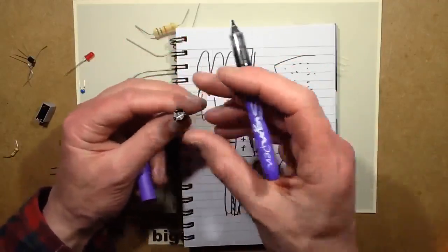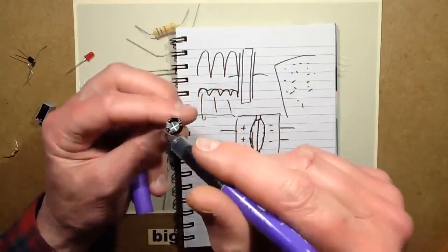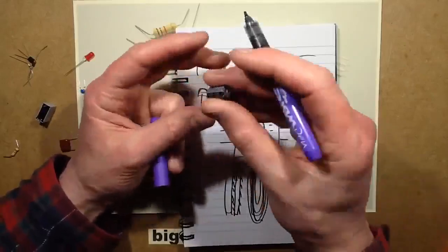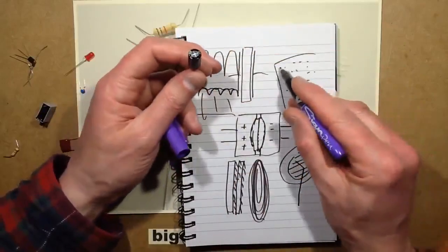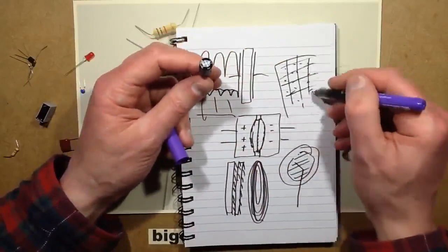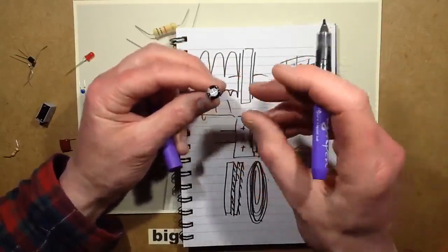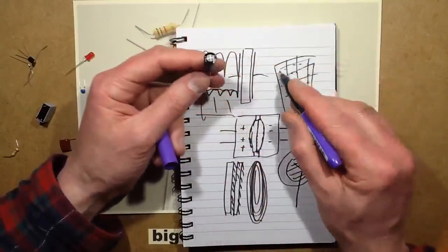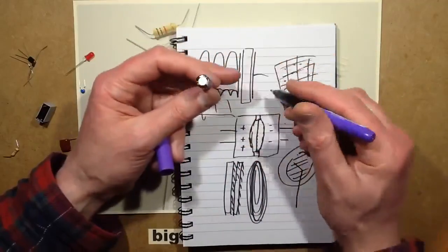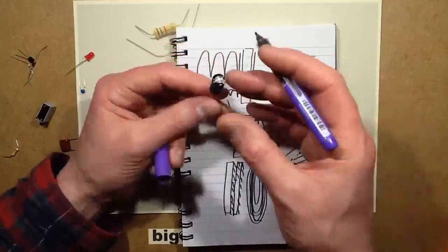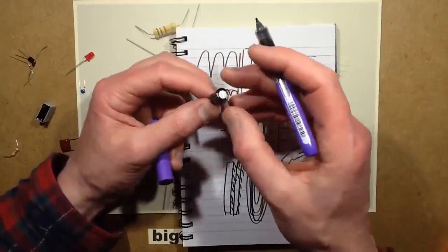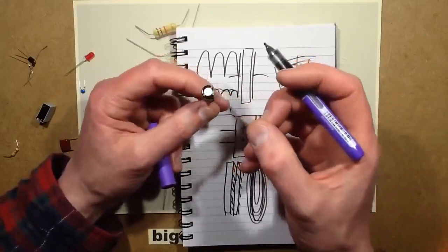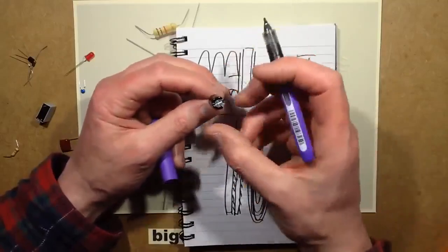They're put under a lot more stress. And if you look at the top of this one, you'll see there's a little cross on it, and that's a safety vent, because when these fail, what actually happens is that oxide coating can be perforated, and that's really common if you accidentally connect them in reverse, because it relies on the polarity to keep that oxide coating intact. When you connect them in reverse, that fails, and then suddenly you've basically got this liquid-filled thing just connected across the power supply with no current limiting it. Basically it turns into sort of a resistor, and it boils the electrolyte.